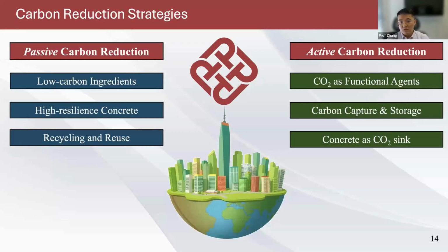And it turned out the results are very good. Those supplementary cementitious materials, that's the official term, short for SCM, can enhance the concrete performance. They not only reduce the carbon footprint of concrete, they also enhance its performance. So in Hong Kong, we are promoting the usage of GGBS.